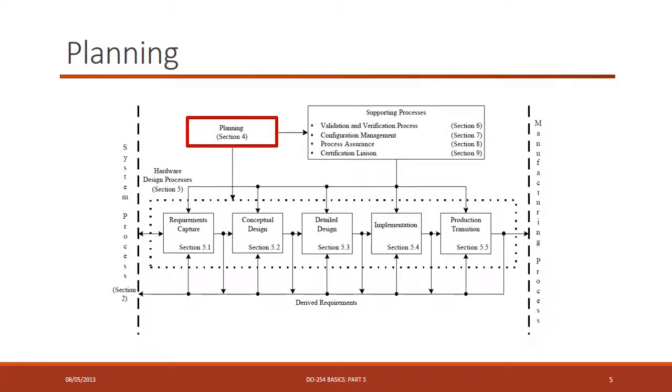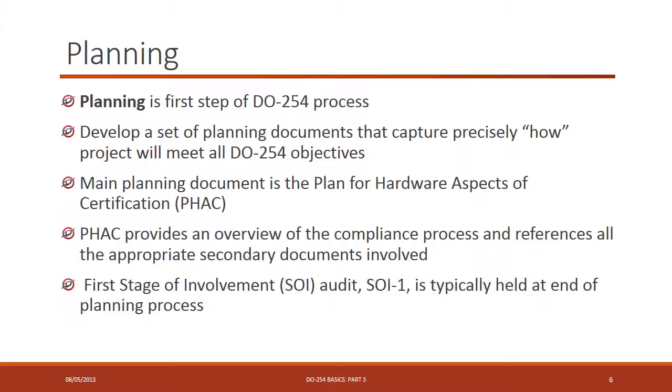The real start of the DO-254 program is at the planning stage. Planning is the first step of a DO-254 process, and during this time the DO-254 applicant and the team of folks working on the program will develop a set of planning documents that capture the how. If you remember, we talked about DO-254 being an objectives-based document. So what you have to meet is specified in DO-254. How you're going to meet it is specified in your planning documentation set.